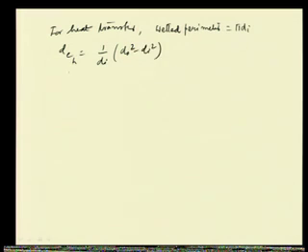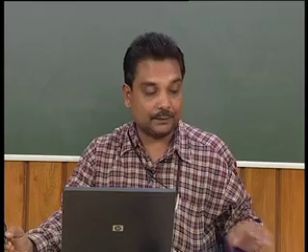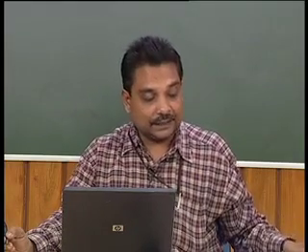Okay. So, this is what we should know, that in case of a non-circular duct we can use the equivalent diameter for calculating the Reynolds number, and then for calculating the heat transfer coefficients by using the Reynolds number expressions in some correlations.